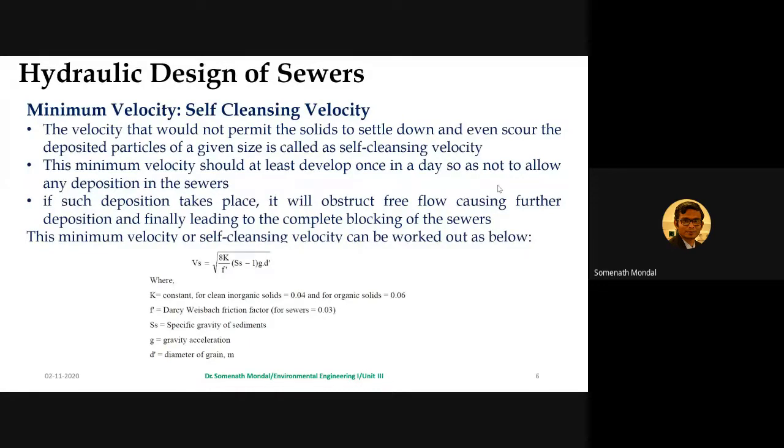And if such deposition takes place, it will obstruct free flow, causing further deposition and finally leading to the complete blocking of the sewers. So this is very important to remember that at least once in a day you should achieve the minimum velocity, just to ensure that there have not been any depositions accumulated within the sewers itself.